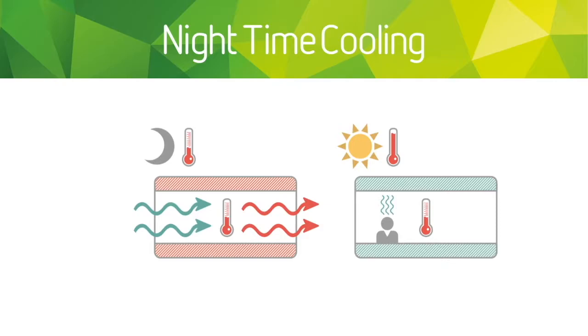If you remember going to a Spanish villa and you walked in and it's very cold during the day, because it's pretty much a bricked up building. This is what we're talking about in terms of using the building's thermal mass to absorb the energy that the building receives during the day. So all it means is effectively at night you let the cool air come in, cool down the building. The building itself becomes very cold, it's a heavyweight building, and then during the day the building itself absorbs the energy, and the internal space can actually still be quite nice and cool and provide a very nice environment.